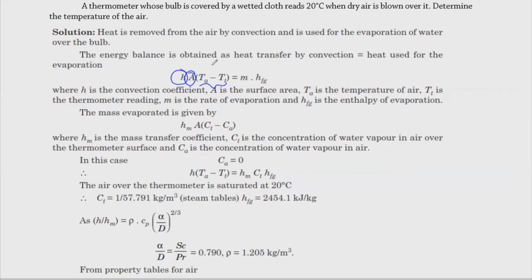So that's basically the sensible heat change that we have. And then we need to find this mass times the enthalpy of evaporation in such case, because water is actually evaporating. So we can also express this in terms of lambda V, assuming that that happens at a certain constant condition of temperature. But for the sake of this expression, let's just use HFG.